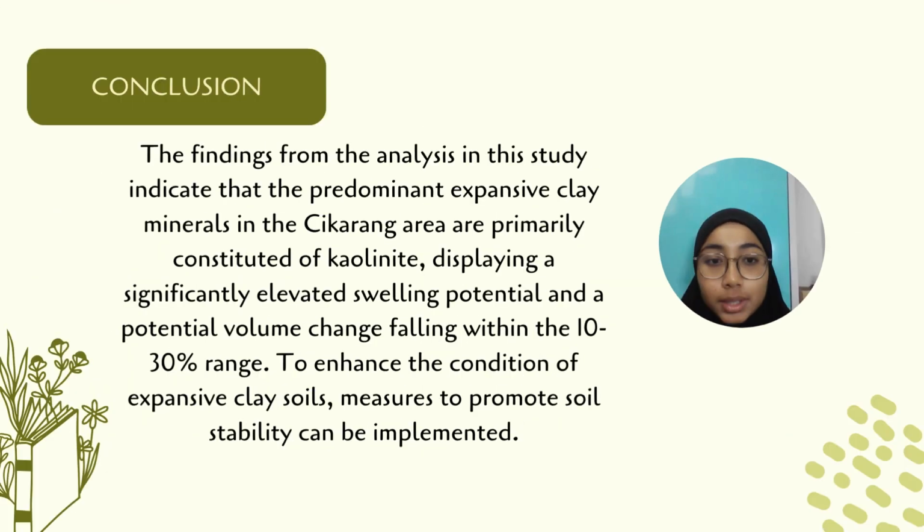The last part is about the conclusions. From these articles, we concluded that the findings from the analysis in this study indicate that the predominant expansive clay minerals in the Cikarang area are primarily constituted of kaolinite, displaying a significantly elevated swelling potential and a potential volume change falling within the 10 to 13% range.